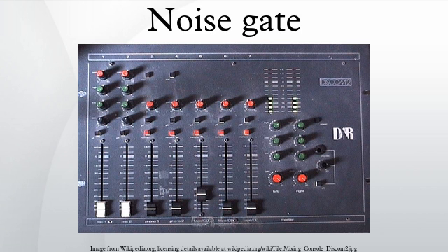A noise gate is used when the level of the signal is above the level of the noise. The threshold is set above the level of the noise, and so when there is no signal, the gate is closed. A noise gate does not remove noise from the signal. When the gate is open, both the signal and the noise will pass through. Gates typically feature attack, release, and hold settings and may feature a look-ahead function.